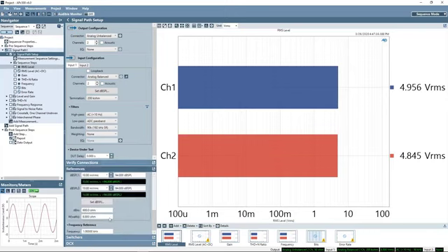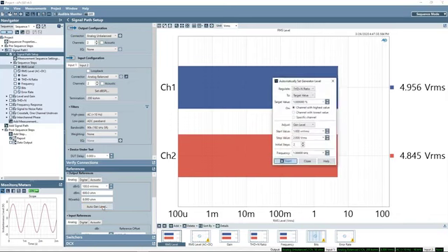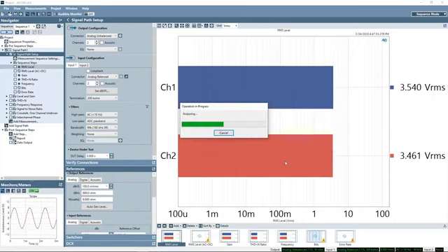Now, I'll show the sequencer in operation. First, I'll use the automatically set generator level feature to find the level where my amplifier makes 1% distortion and set that level as the generator reference, also known as 0 dBRG.